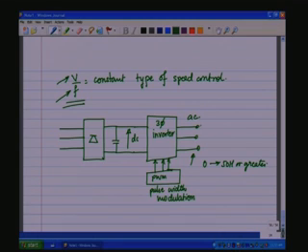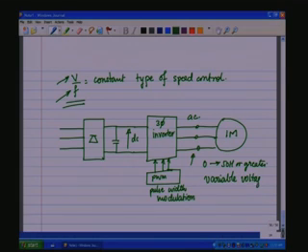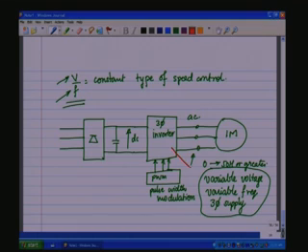The modulating signal will be applied to the induction motor, which can get variable voltage, variable frequency, three-phase supply by means of this inverter, and therefore the frequency can be controlled, and you can have V by f type of speed control, and you can have a whole speed range right from close to 0 up to even over base speed or over 120 f by P.